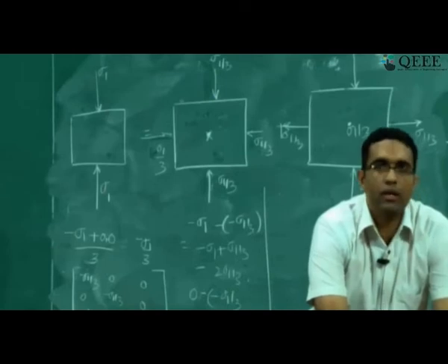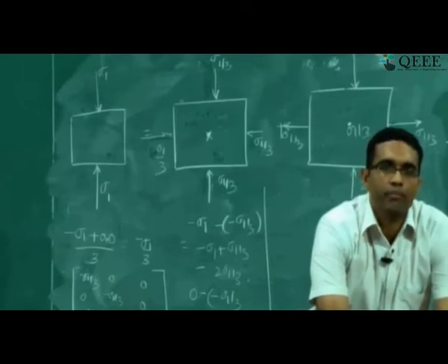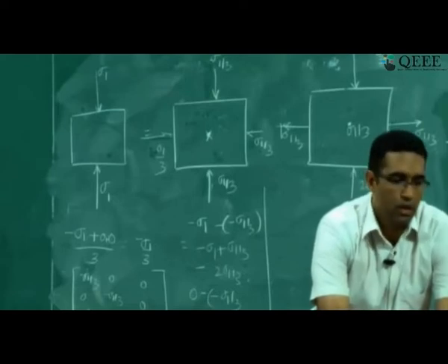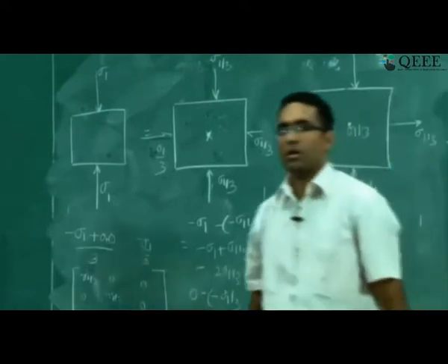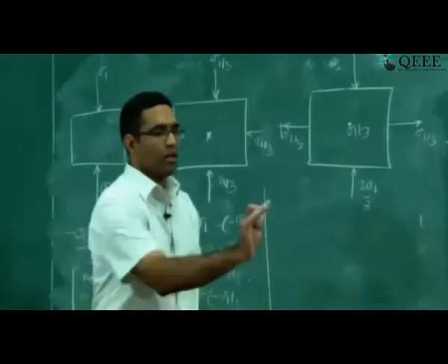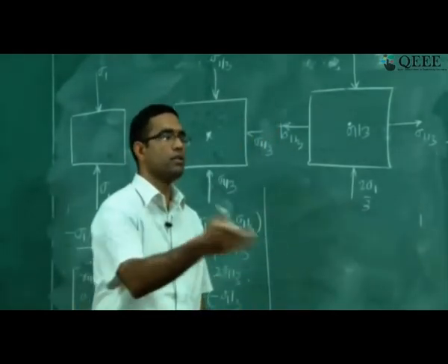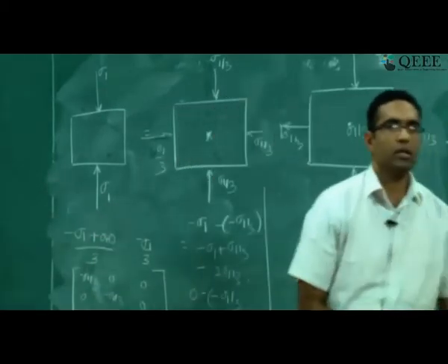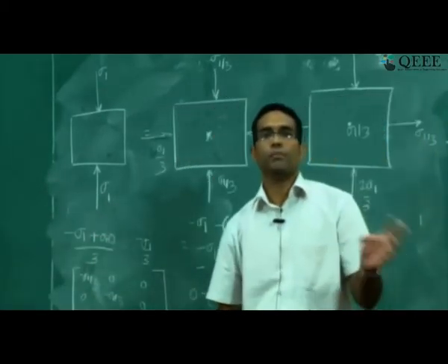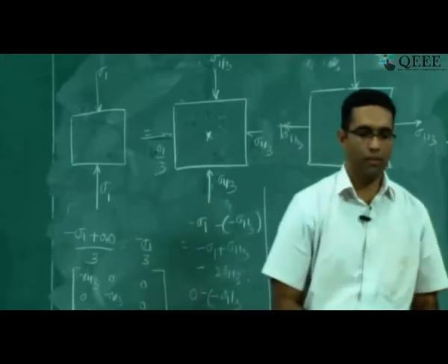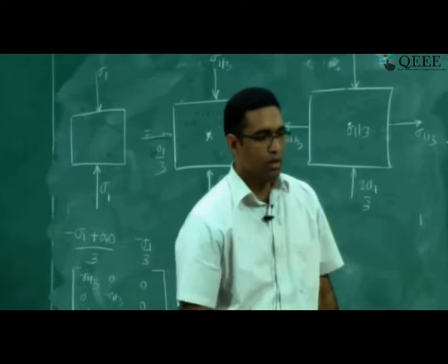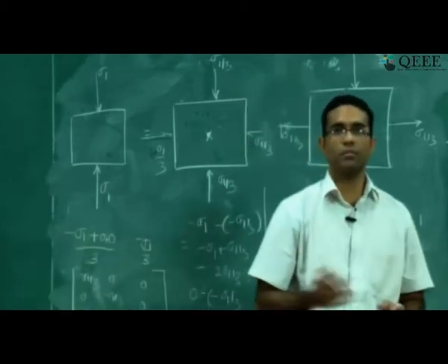The first invariant, what will be the first invariant? It will be 0, right? Because you are summing the diagonal components, so if you sum it, you will get 0. But the second and the third invariant have the same definitions. The third invariant is the determinant, and the second invariant will essentially be the sum of the principal minors. So let's go ahead with the next part.